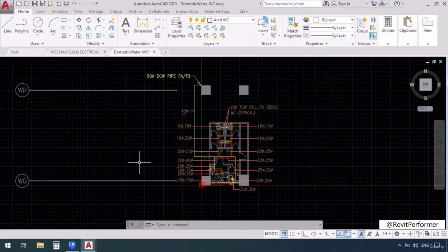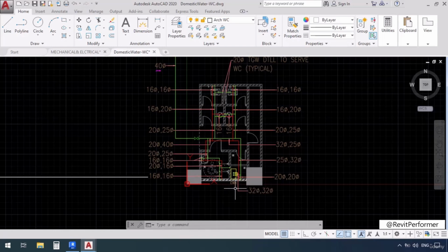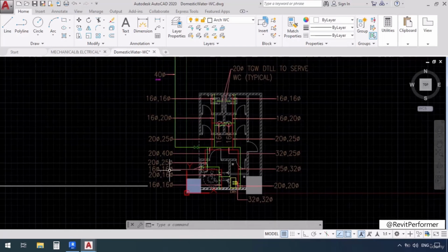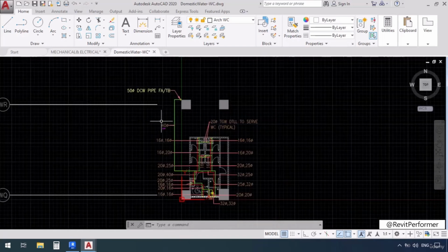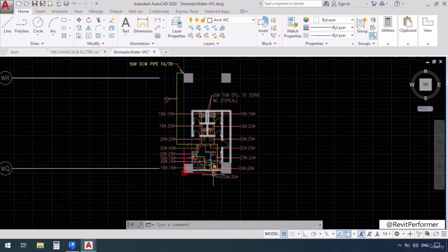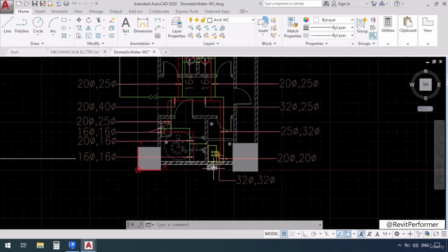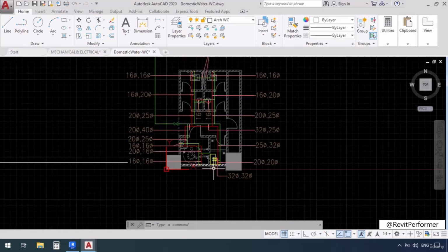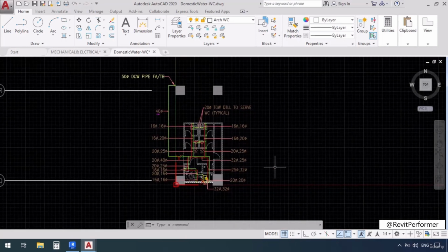The way that this plan was designed is actually meant for when these equipments are not very frequently used, or it might be because this area is too far away from the mechanical room that it wasn't worth investing so much on putting so many pipes and the whole process of hot water return and supply. So what happened instead was that an electric water heater was placed here at the very bathroom area. The only thing entering the bathroom is the cold water pipe, and that cold water goes to the water heater to become heated. So this was a different type of plan which we could come across.